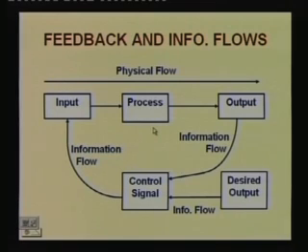In another word, a negative feedback loop is one where we are trying to achieve a balance, where the output is trying to reach the desired output. It doesn't outgrow the desired output. If the output is below desired output, the control signal is positive and it therefore requires more inputs, whereas if the actual output is more, the control signal is negative. Because the control signal is negative, we actually reduce the inputs so that output falls to the desired output level.